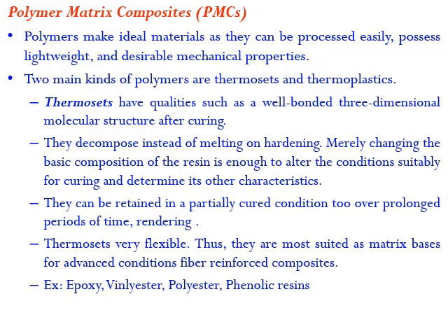They will just decompose, or else they will degrade, or they will get evaporated rather than coming into the molten state. Depending on the basic structure, the molecular structure, or how the monomers are bonded, the remaining properties are defined. You can say they are well bonded with a three-dimensional molecular structure, so they decompose instead of melting. They can be retained in a partially cured condition over a long period of time.